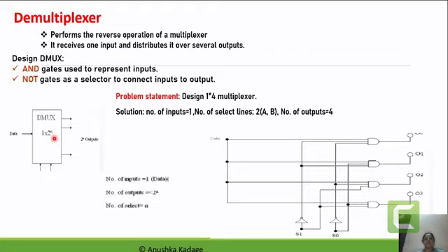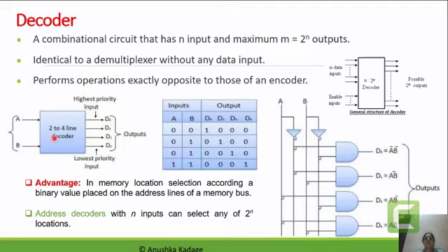Always, a multiplexer or demultiplexer will present a single output or single input line. While in the case of encoder and decoder, on both the input and output side, a different number of variables will be present. It is never a value of 1 for either input or output in an encoder or decoder.